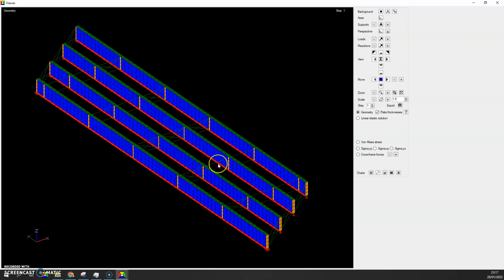Lean-on bracing is more useful for cross-frame design in a way to provide just enough stiffness to not attract too much load in those cross frames, to keep their sizes to reasonable dimensions. Okay, but for thermal loads, there's not a clear benefit in any form.